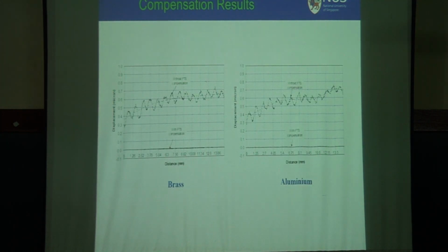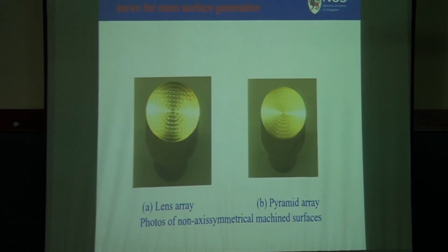This was the surface roughness. So that way you can measure the surface roughness as well as straightness, and you can compensate both. And the surface roughness and straightness are measured using a capacitance sensor. With a reference surface, the capacitance sensor takes care of the measurement of deviation. Then you can compensate.